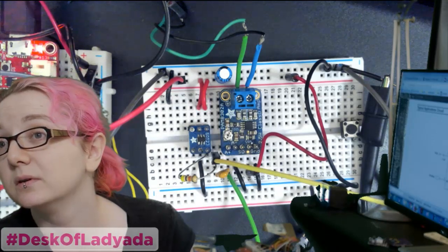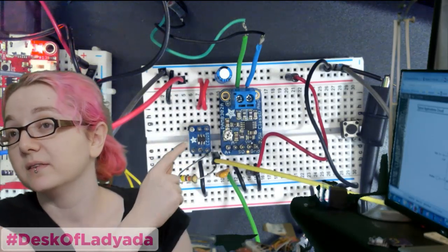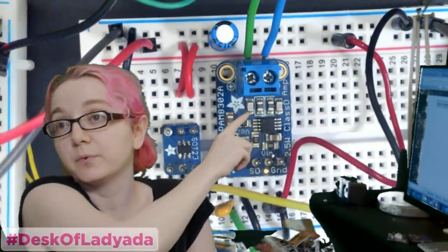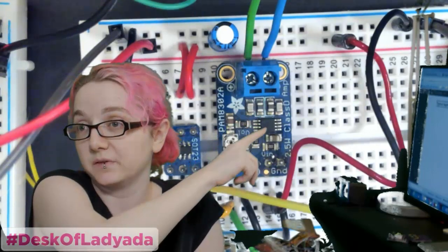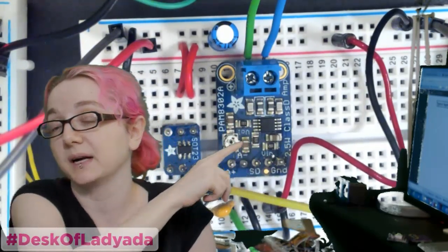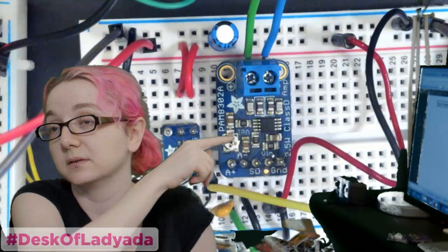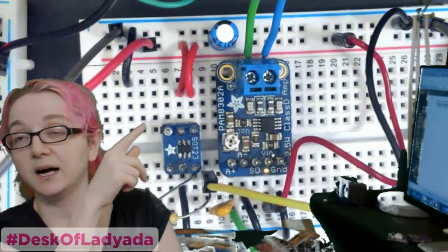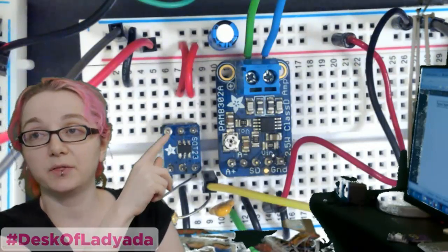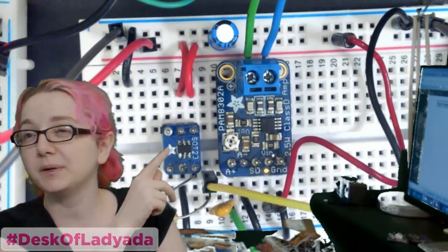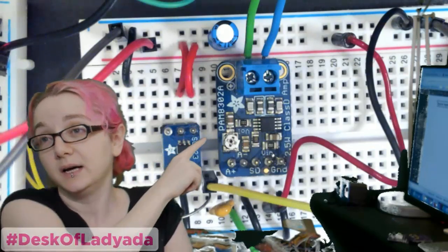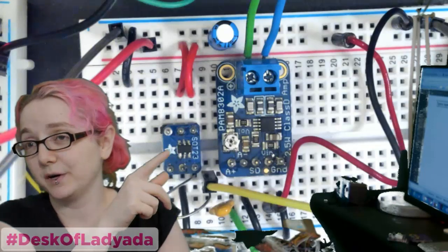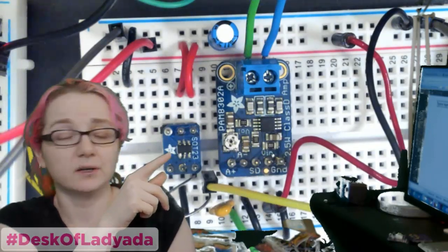Yeah, that's cool. So this is, I'm basically trying both and comparing them. Even though this one has more circuitry, I might desolder some of this so I can have a more realistic comparison, because I'm not going to have an audio level potentiometer. And then this is the PAM 8301, which is a little bit less expensive, but it's also a lot smaller. Although this one does come in a DFN, it's hard to get in a DFN. So this might be a lot nicer.